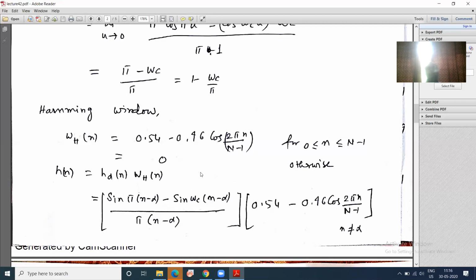Therefore, different window techniques are used to achieve the ideal characteristics in the passband to stop band transition, as near to ideal as I can reach. So the techniques are different window techniques. That can only be understood if I design the same filter using different techniques and then plot the response in MATLAB. Then you will see that the transition will be different for different window techniques. So essentially, different window techniques ensure different passband to stop band transitions.